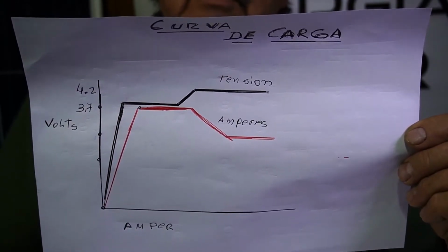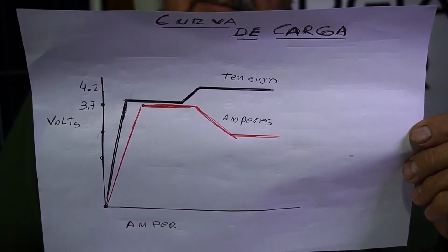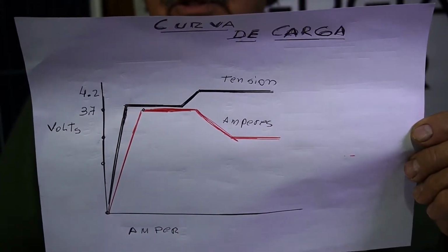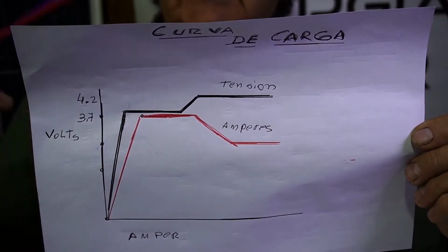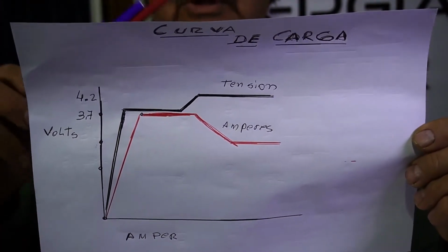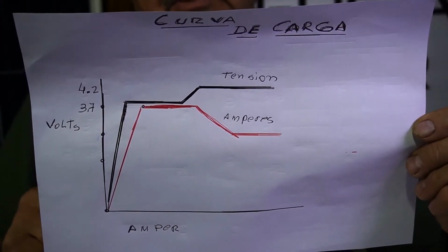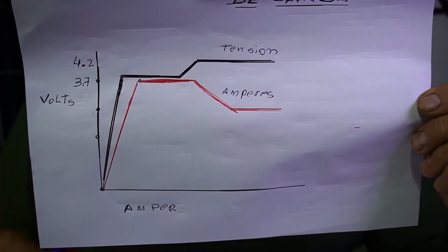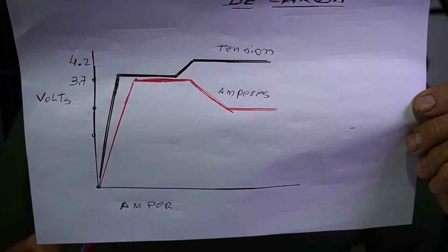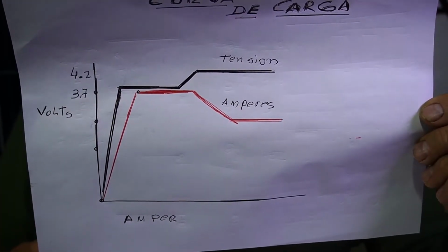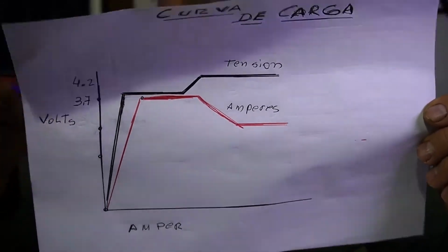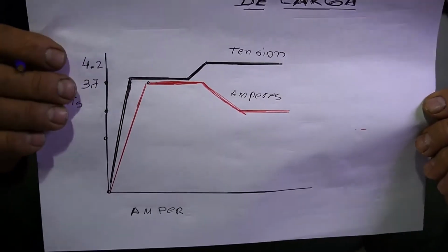If we charge it too quickly, we will deteriorate it or we will raise the temperature. I explain all this application because there are many informative videos about this where they talk about how to apply a charger to a certain battery. With this, I explain to you so that you have a broad knowledge of how to do it. Also, how to do the charger. The most important thing are the controls, because I already said that the battery cannot exceed a certain charging voltage, which is 4.2.